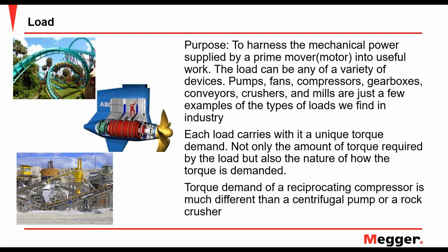The load's purpose here is to harness the mechanical power supplied by the motor into useful work. And again, the load varies a bit. Pumps, fans, compressors, gearboxes, conveyors, crushers, mills are just a few. Bet you guys could come up with a few too. Each load carries with it a unique torque demand. Not only the amount of torque required by the load, but also how it's required, the nature of it.